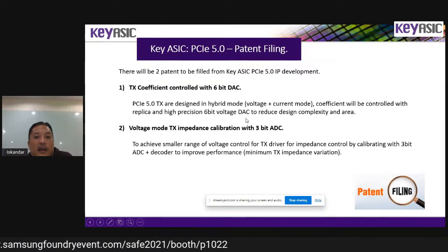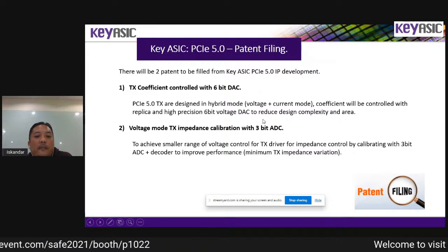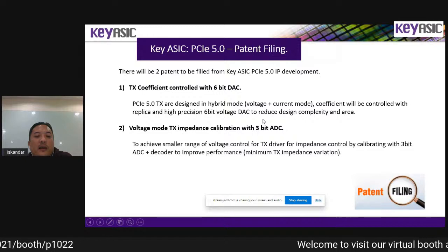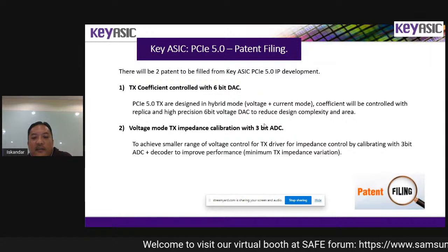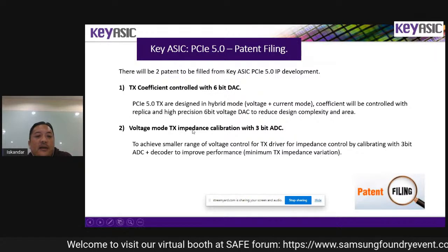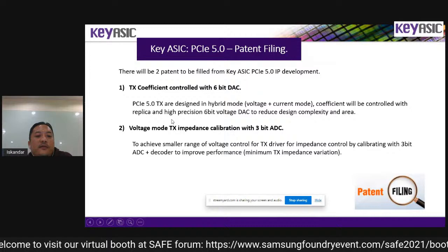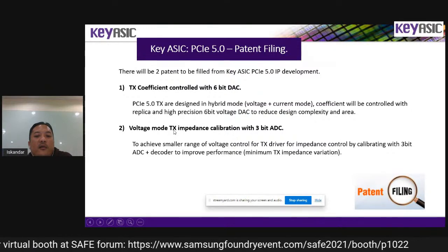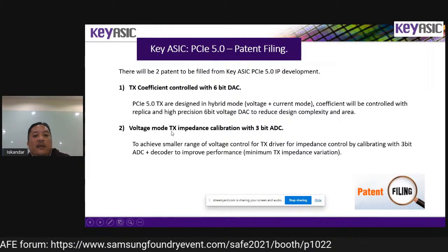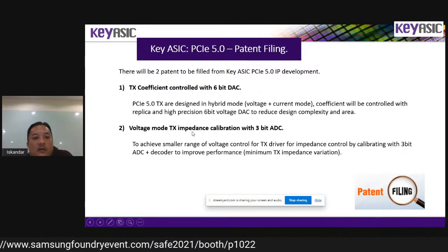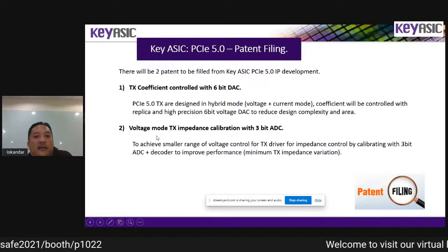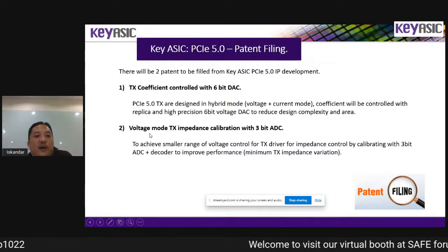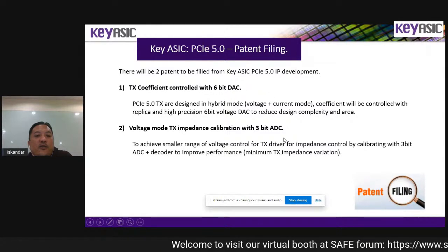So we use the ADC to control the analog side of the driver to calibrate the driver impedance to remain always 50 ohm at PVT condition. We plan for another patent for this project, but so far only these two are official ones.